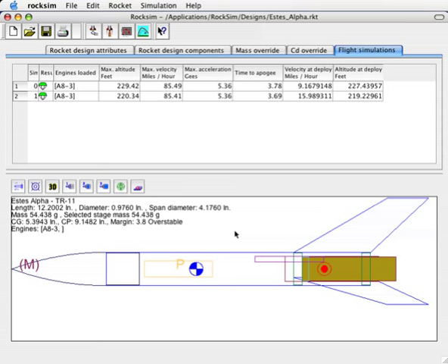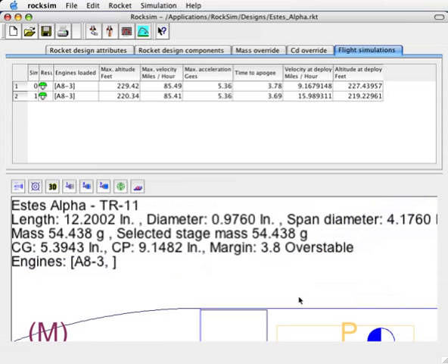In this video, I want to talk a little bit more about the preferences that you can change, along with some things that aren't readily apparent. For example, here in the 2D view, we can zoom in on certain parts. To do this, if you're using a 3-button mouse, go ahead and click on the right button, and that will bring up a little menu that allows you to zoom in.